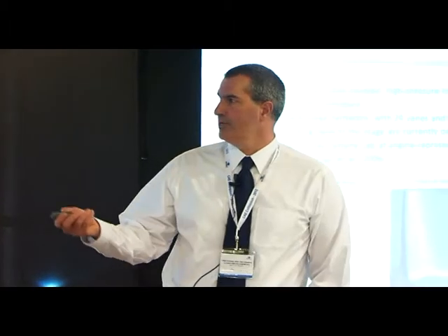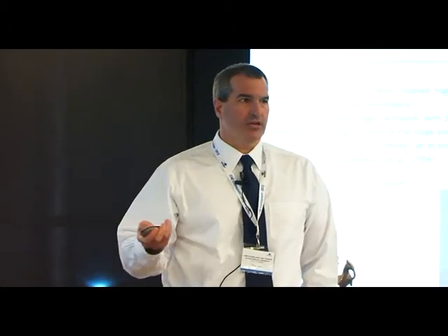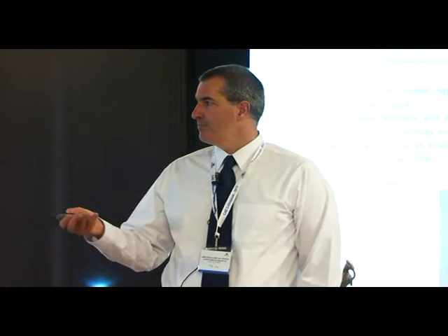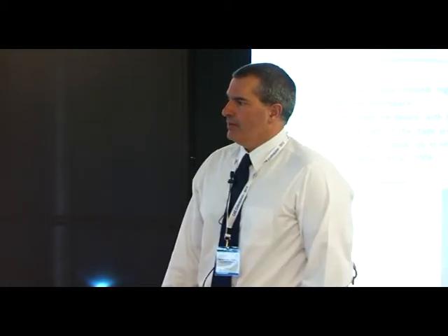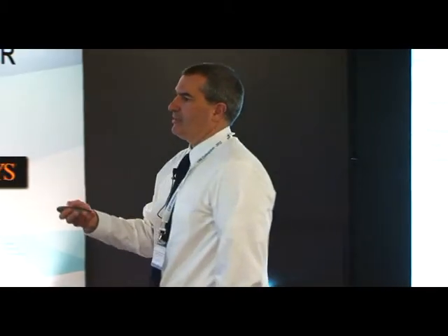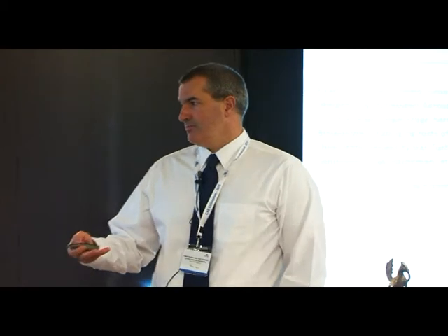So the specific airfoil we're interested in was designed by Honeywell Aerospace. It's a bizjet engine airfoil, and that's the actual airfoil right there. We were simulating a test condition. There's a blowdown test facility at Ohio State University where they test these full-scale engine components at full speed, and there's measurements taken off of that which we'll compare to.